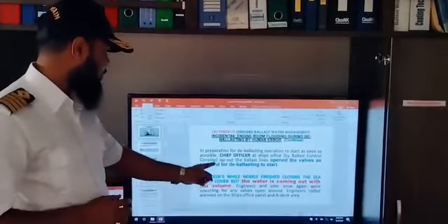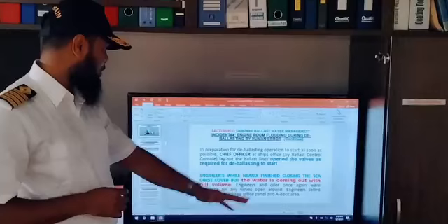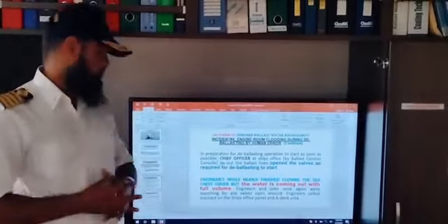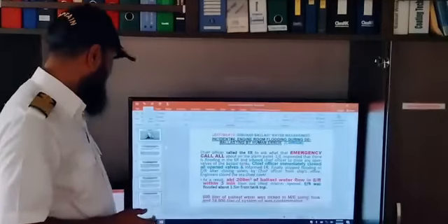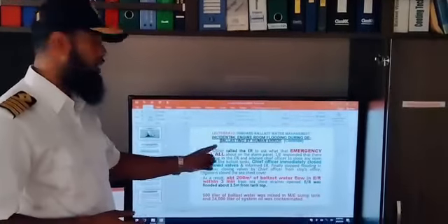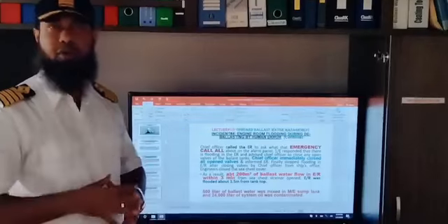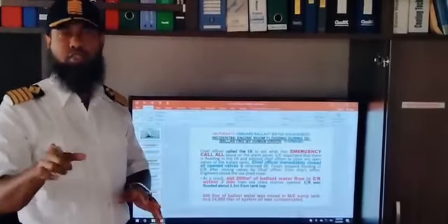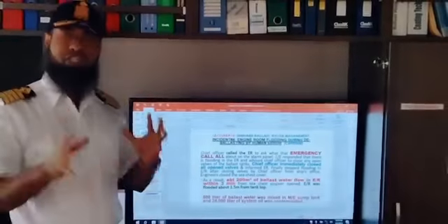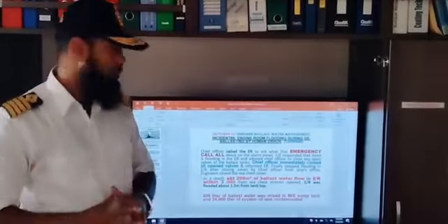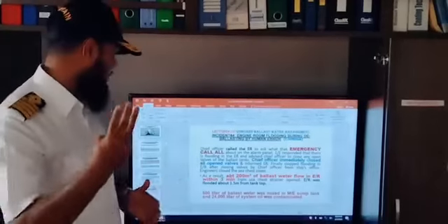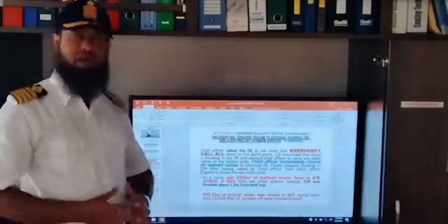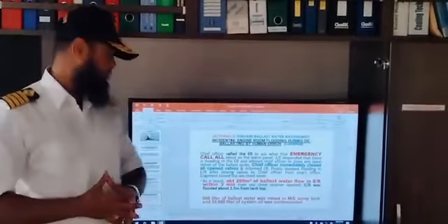Immediately, while the engineers were nearly finished closing the sea chest cover, the water came out with full volume. So they immediately raised the emergency call, all alarm, and called the chief officer that the engine room was going to be flooded, asking him to close any open valve. The chief officer immediately closed all the valves, but within 3 minutes only, about 200 cubic meters of ballast water was already inside the engine room.